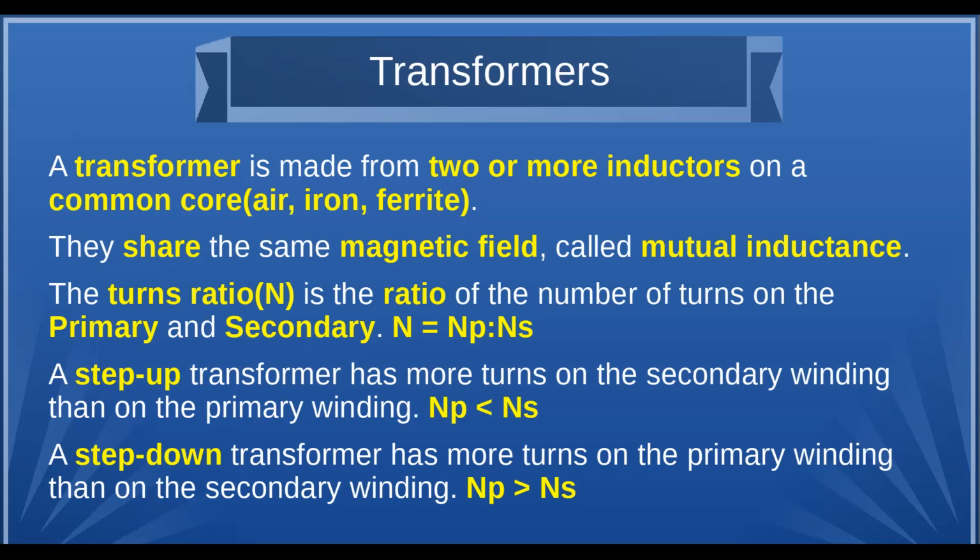Now, because transformers have no gain, it just transforms. So if I put a watt into that transformer, the most I can get out is 1 watt. So if I'm getting twice the voltage out, I'm going to have to get half of the current out. Likewise, if I got half the voltage out, I'll get twice the current out.